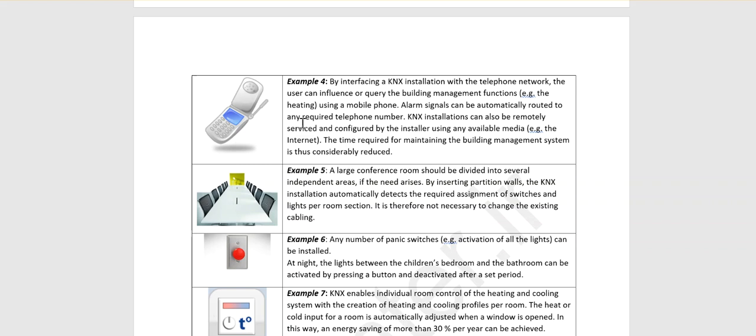Nowadays the telephone has almost vanished. Most notifications go through email. In a large conference room or large open office, you can use KNX. For example, use presence sensors on the ceiling to divide the big open office into different areas, and control the light and HVAC depending on the presence of people in that room.